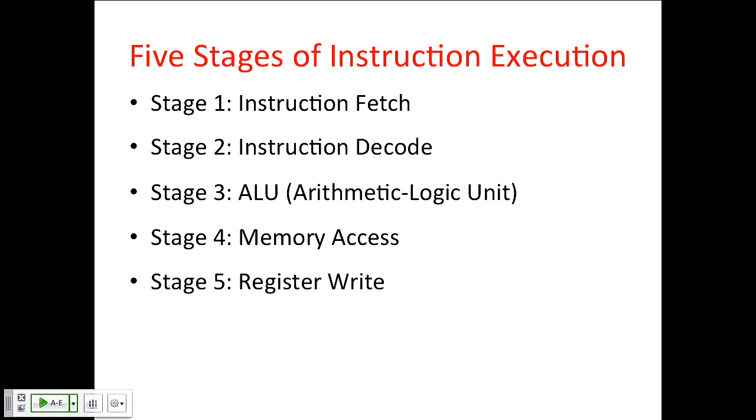First stage is instruction fetch. Second stage, instruction decode. Third stage is ALU. Fourth stage is memory access. And fifth stage is register write. These are the 5 stages all the instructions go through. So I'm going to dive through those one at a time.